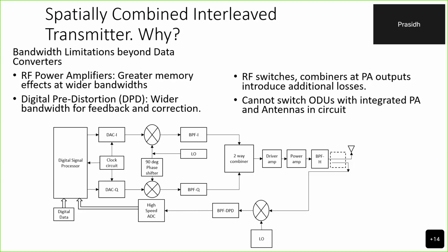The non-linearity is essentially going to result in spectral expansion. Say one has a channel bandwidth of B, then the third and fifth order non-linearities are going to expand the overall bandwidth of the output signal to something like 5B. This implies that one is going to encroach into the neighboring spectrum, which can result in legal actions. Secondly, when it comes to things like SATCOM, usually the modulator remains indoors, and the upconverter and the output power amplifier remain in the outdoor unit. So one cannot do a switching arrangement mainly to enhance bandwidth if needed.